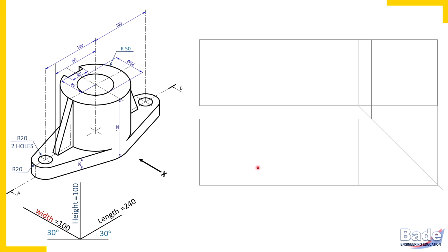Let's focus on the top view. So curved edges first, then principal edges, and then non-principal edges. Do you remember the procedure I've given you? So let's proceed. To draw these curved edges on the 2 sides, we'll locate center of the curved edges. So width is 100 millimeters. In the top view, don't forget width is vertical. So I've located midpoint 50 millimeter and I've drawn center line. So this is a center line passing through the centers of these 2 holes, that line we have located.